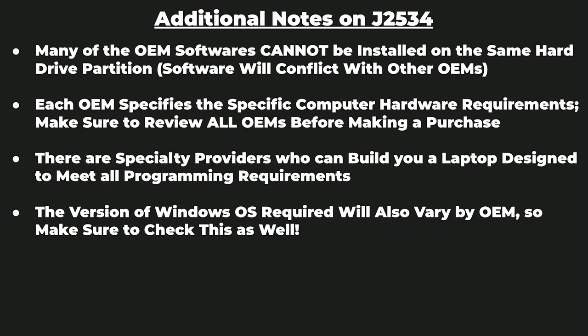They will interfere with each other. So if you are trying to do programming and you have Ford and Volkswagen on the same hard drive partition, there is a high likelihood that there will be an issue and you will not be able to conduct programming on either Ford or Volkswagen because the drivers may interfere with each other and the physical software may interfere with each other.